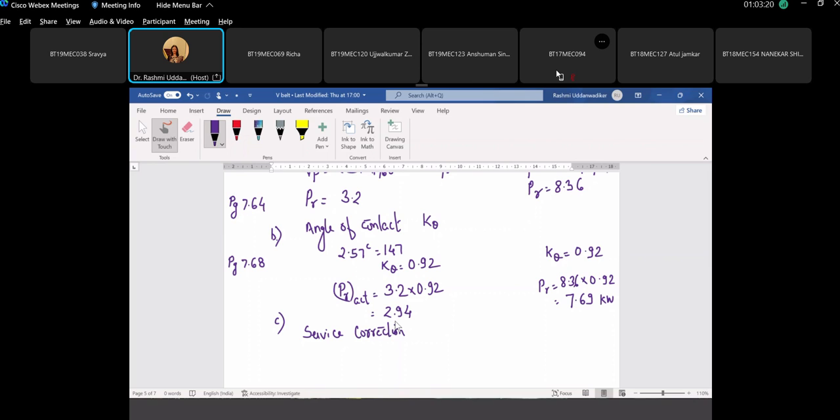The type of driving unit is a motor running at more than 600 RPM. So it is the second column for 12 hours per day. So what is the value? Heavy duty AC motor, 12 hours per day. It is 1.5. How are you getting 1.3? It's rotating at more than 600 RPM, the motor RPM is given as 1440. You have to pick up the second column. The first column is for motors running below 600 RPM. So we are going with 1.5.